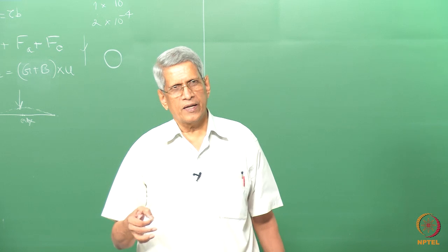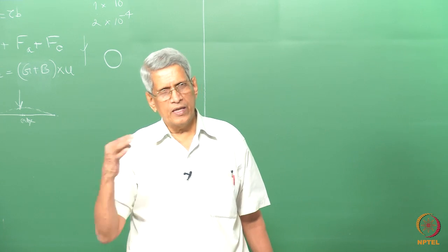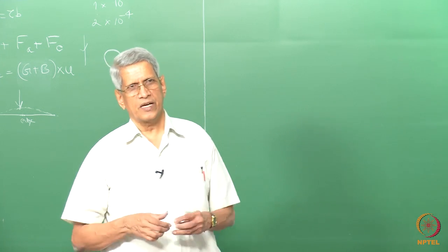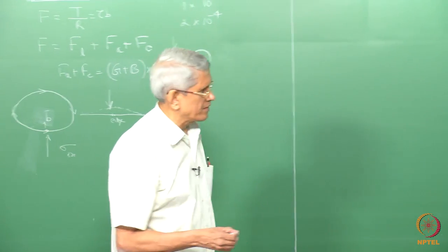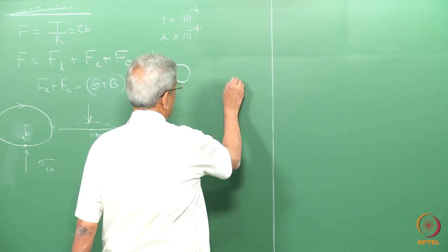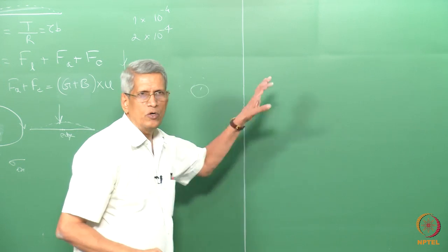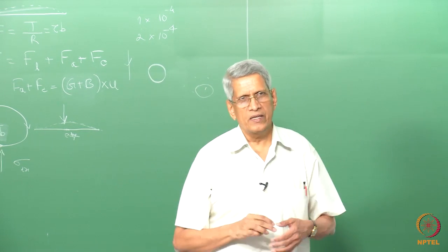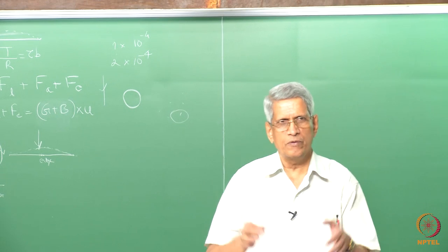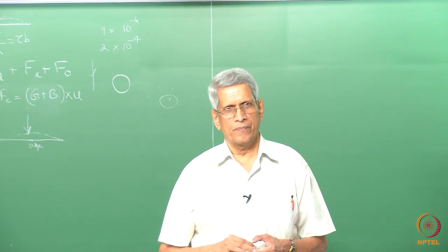This excess dislocation density arises because, when the vacancies cannot equilibrate, the only way to relieve the high stresses generated due to excess vacancy concentration is that vacancies which are close by in some region all come together and condense, and a small loop will be formed. That is the way they can relieve these stresses. Okay. This we will observe in the material.